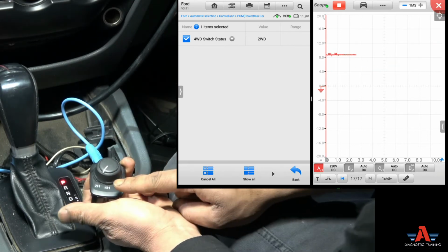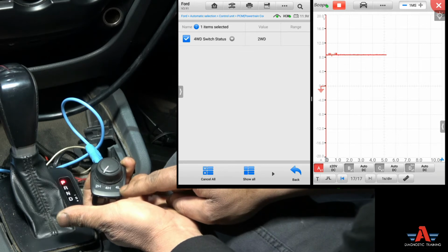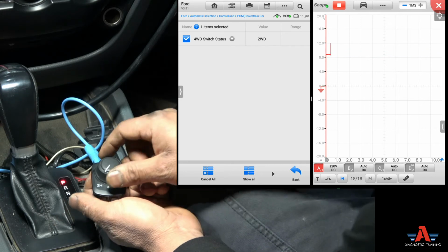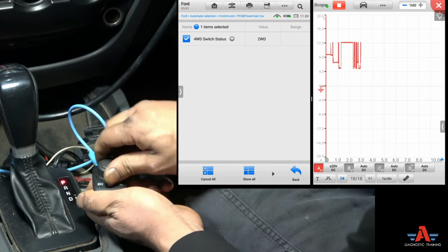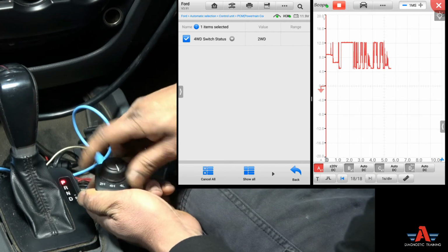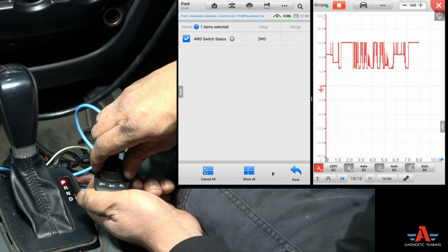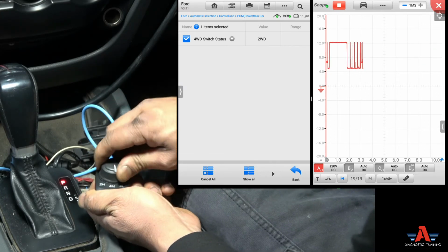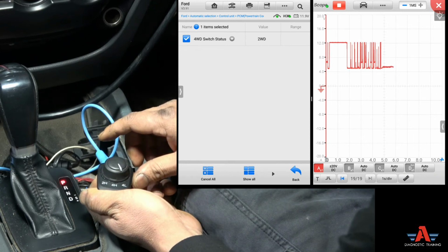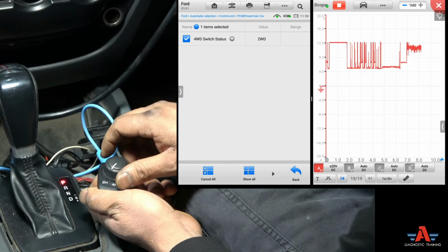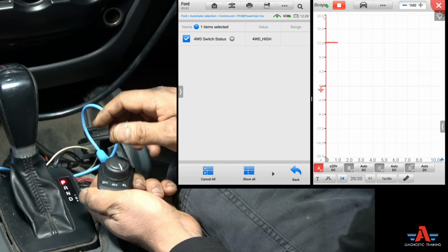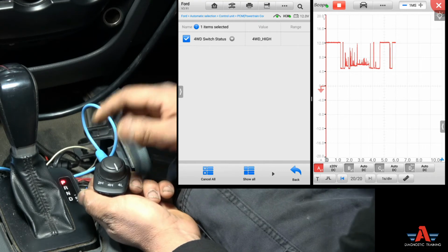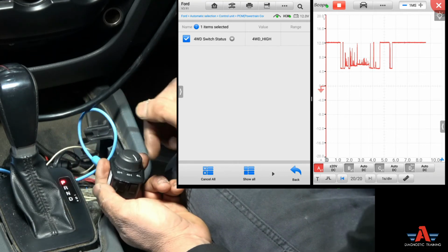That's 2-wheel drive. So I think just someone spilled a drink or something in there. Whatever happened, the corrosion did some damage there. This switch is not in the best condition, but it kind of works now. Just that last position, the 4L, is still a little bit not right. But anyway, customer's gonna need a new switch.